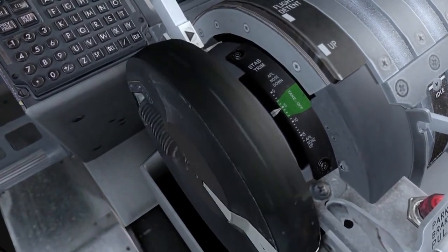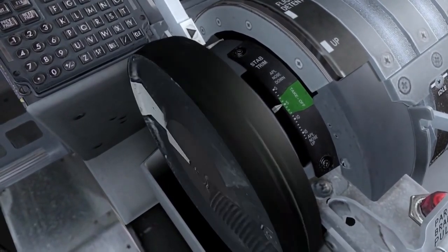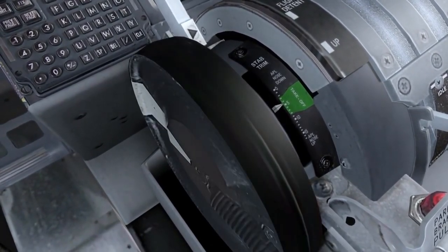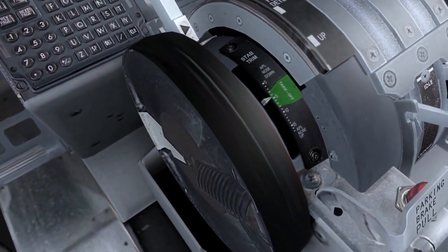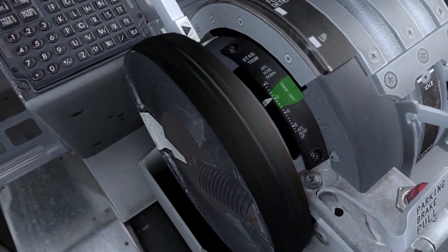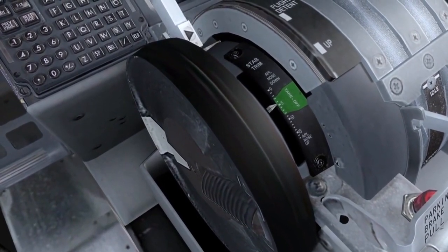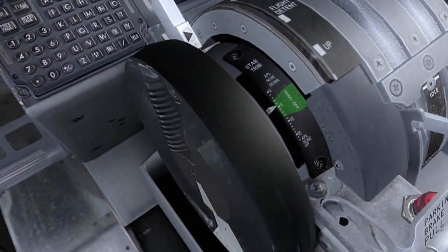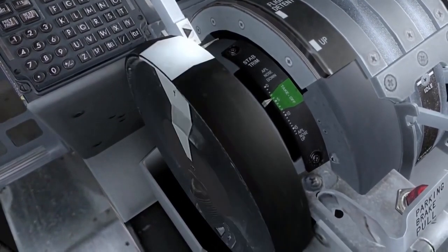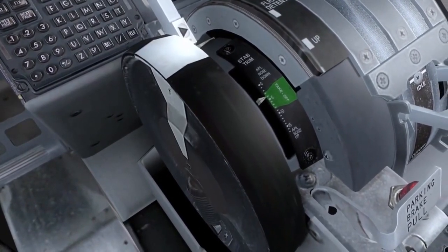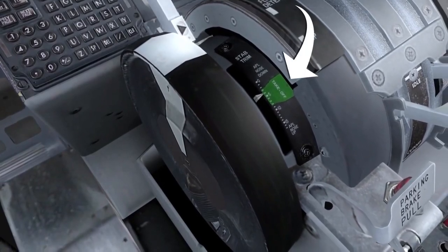The stabilizer trim limit switches limit the range of stabilizer travel. There are different limits for manual, autopilot, flaps up, or flaps down operation. There's also a takeoff warning switch that alerts for incorrect stabilizer trim configuration during takeoff. The cockpit stabilizer trim indicator has a green band to show the takeoff trim range.